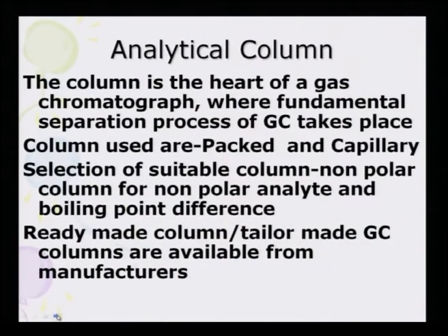Analytical column. The column is the heart of the gas chromatograph where the fundamental separation process of GC takes place. Column used could be of the packed type or the capillary type. Selection of suitable column: non-polar analyte uses non-polar column, and the boiling point differences should be much different. Ready-made column, tailor-made column, as I mentioned earlier, must be chosen from the catalogs that are already available, so that one can design the analysis and do it accordingly.